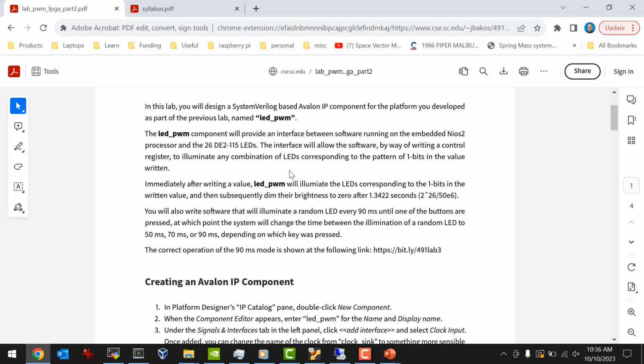And then you can just use that value as your duty cycle, right? Does it make sense? Not the whole value, you may just have to use the upper bits of it, but basically that will represent your duty cycle. So the CPU will be able to hit individual LEDs, and every time it hits one of those LEDs, it'll go bright and then dim.